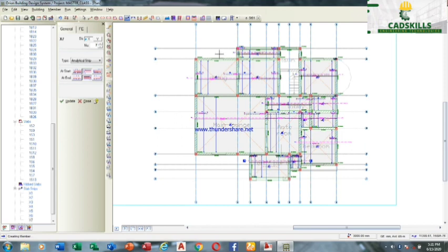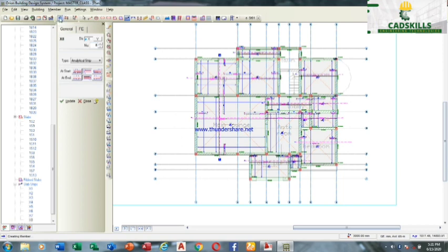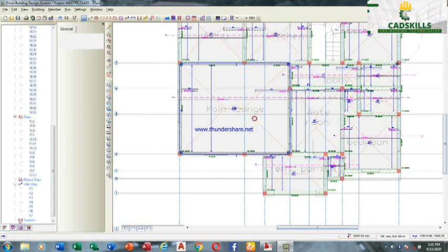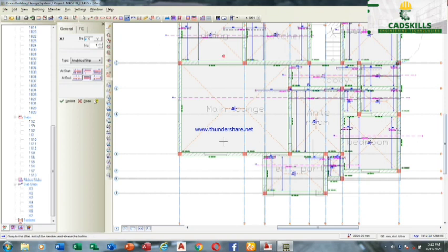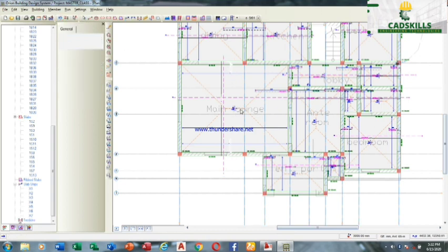So what you do horizontal, you do vertical also. You put your reinforcement vertical. None of you reminded me of something. This slab is supposed to have beam. He's telling me that the section of the slab is too much, that it failed. That is what he told me. Let me do it again, because you may encounter such a thing, so that you know what to do. Look at what he said. Deflection occurred. So you need to put beam somewhere so that you can reduce the span.